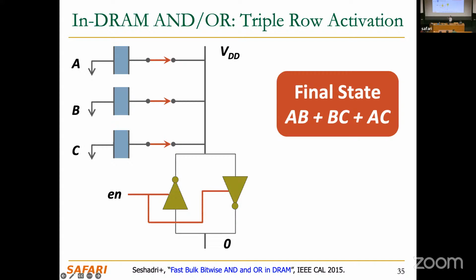So if you replicate this 6 times in 6 rows here, so replicate it 2 times, if you do the math for the sense amplifier, you are back to the original sensing capabilities of the standard sense amplifier in the DRAM chip itself. And you can replicate it even further to further improve the success rate. Of course, this comes at the cost of storage. But it's one way of improving the computation reliability in current DRAM chips.